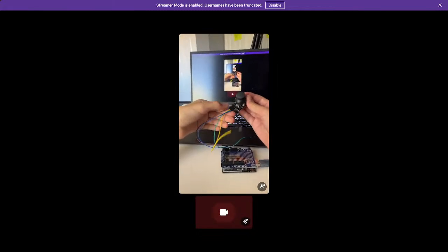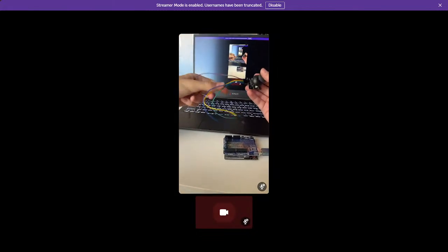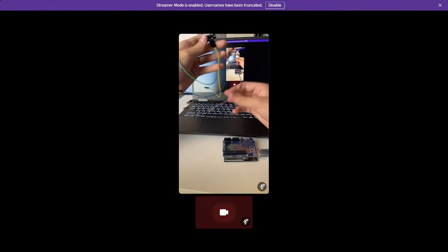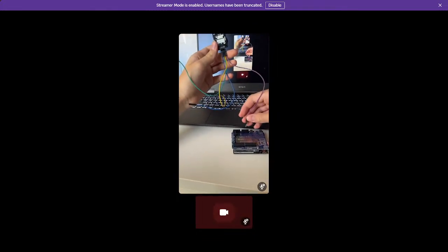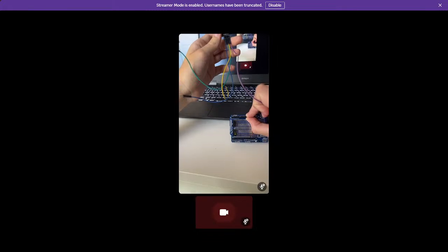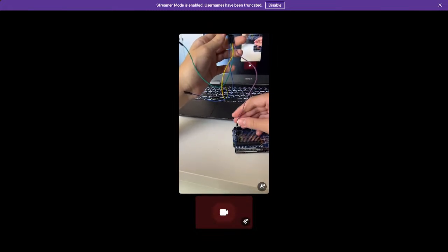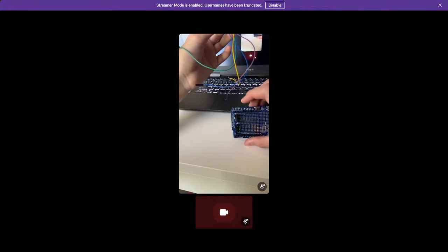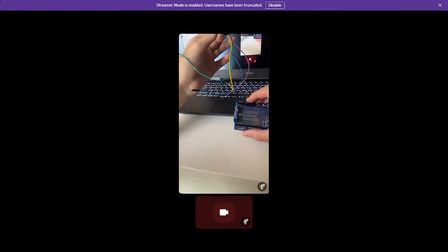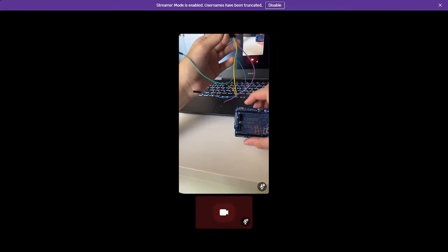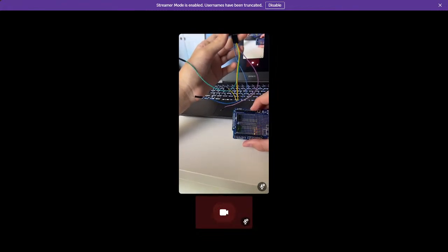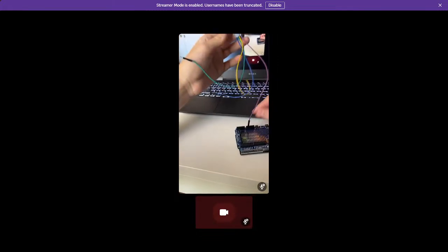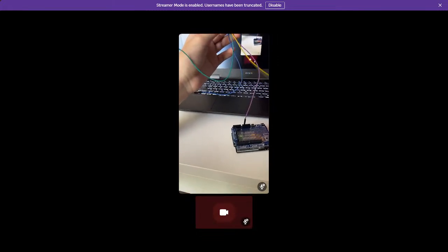So, we got our X and Y pin and our ground and 5 volts pin. So let's plug in the ground and 5 volts first. This purple one's ground. So we're just going to plug that in straight into the ground pin. We can just use these for today. If you don't know, I'm using little expansion, so I have more options to choose for with 5 volts and ground. Typically there's only one pin for 5 volts, which is annoying, to say the least. So this should be ground. This is 5 volts.